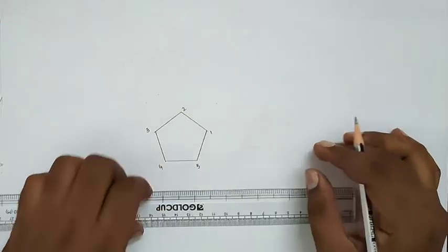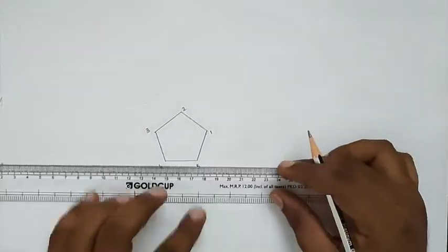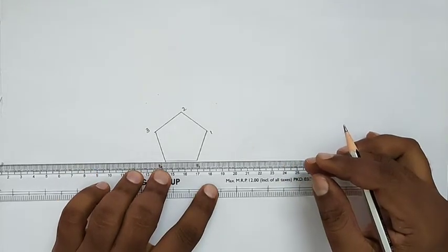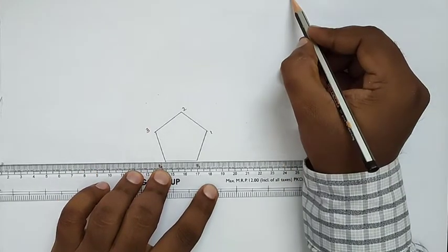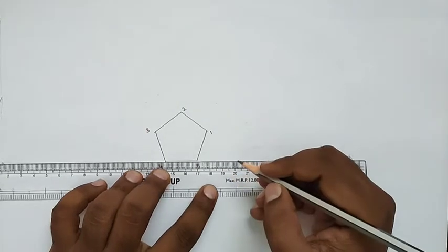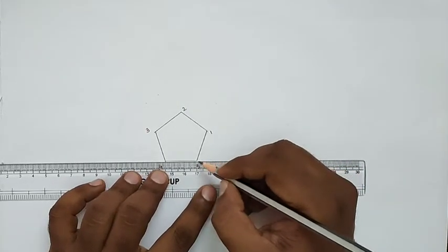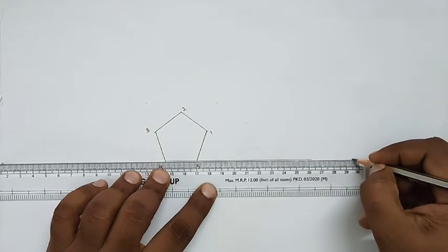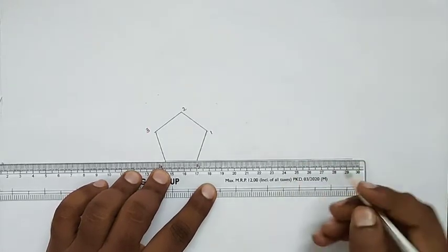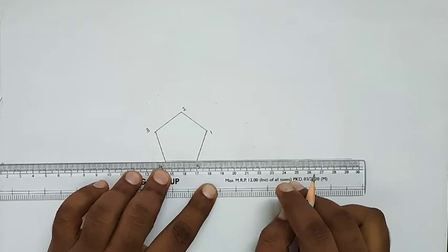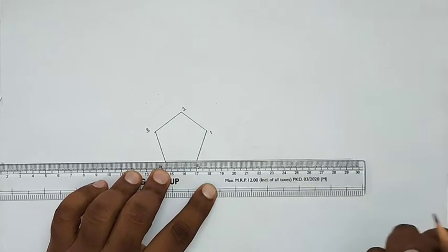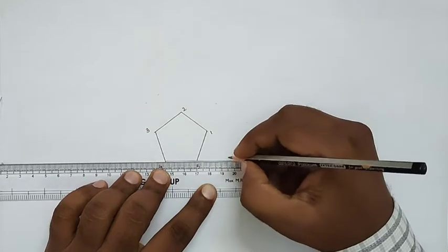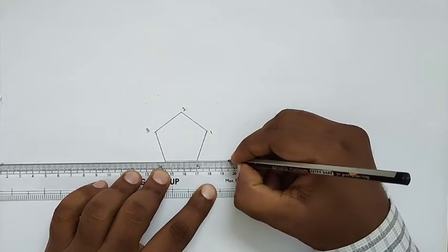After drawing the pentagon, the length of the string they are giving is 110 mm. So with the perimeter of the pentagon, 125, we will draw a horizontal line, 125 mm length you can follow. After drawing it, we will divide that perimeter into 5 parts, each part being 25.